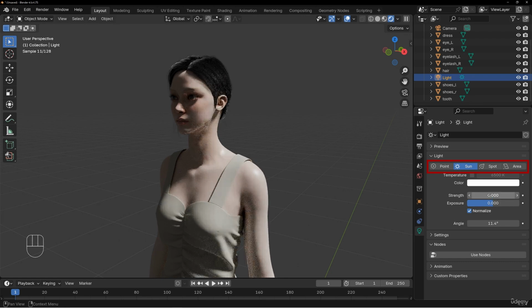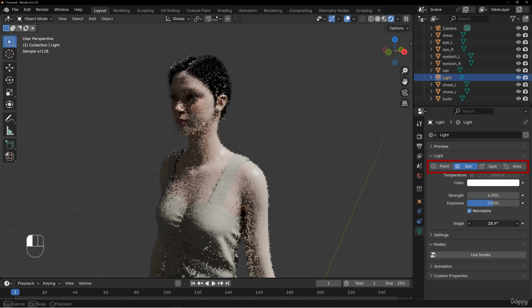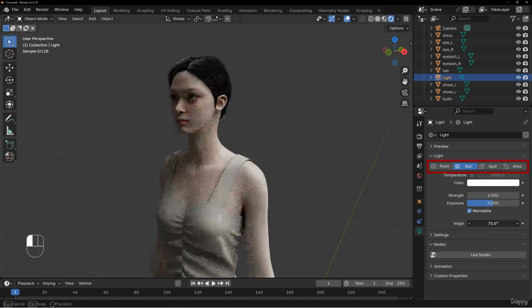Within the light settings, you'll find an angle option. Adjust this to create an angle where light hits from slightly above and to the side. This makes it easier to check textures. Since this is just a simple work light for now, no need for fine-tuning. We'll cover full lighting setups and HDRI usage in detail in the Blender Advanced Techniques section.